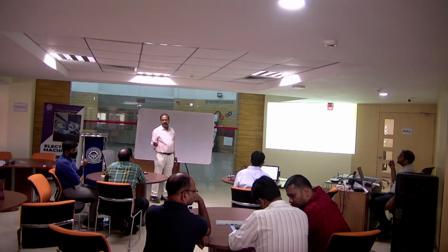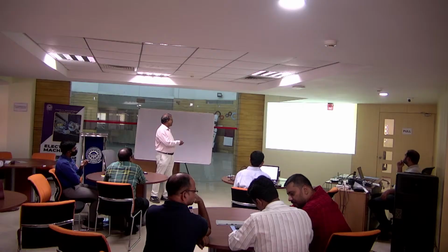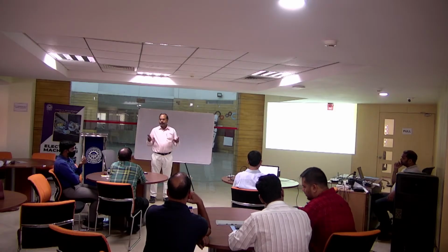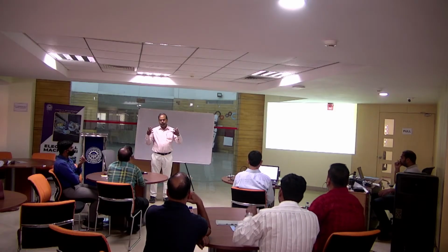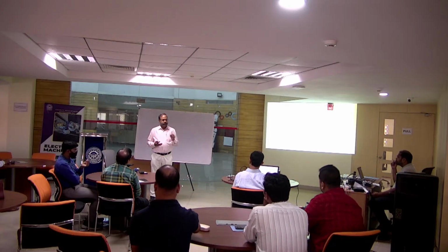Because there will be losses in the resistance, efficiency is poor. Then speed control by cascade method. In the cascade method, we are connecting two motors in cascade. Cascade means, suppose you have two slip ring induction motors. One induction motor starter you connect to the supply.